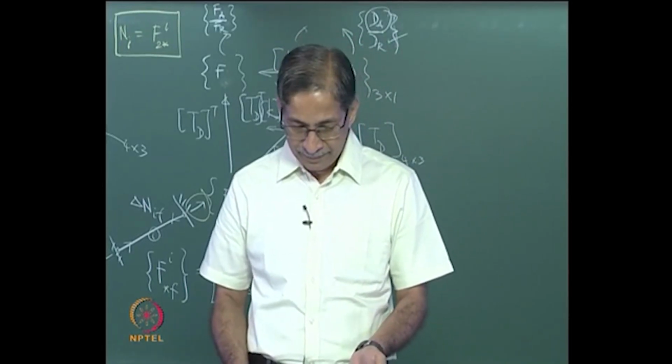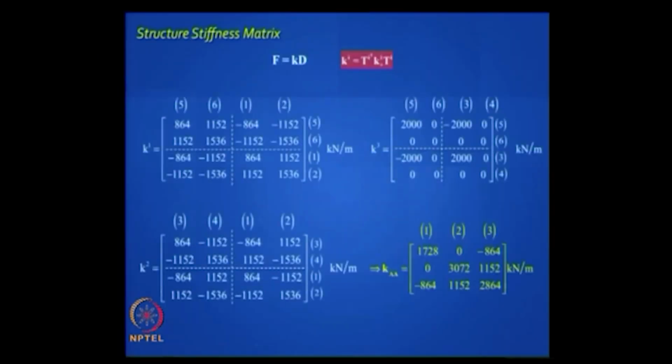You do that and you get this. Okay, you get this. From this, how do I generate my final answer? So what's the size of my structure stiffness matrix? 6 by 6, right? 3 active degrees of freedom, 3 restraint degrees of freedom. So let's just pull out KAA.